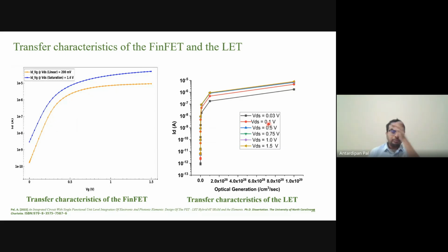Thank you. So this is the transfer characteristics of a FinFET and a LET from simulation. So in your transfer characteristics, you know, it's the drain current over gate voltage, right? At different drain voltages. So this is for the FinFET, and this is exactly for our LET. Now, you can see they're very similar.